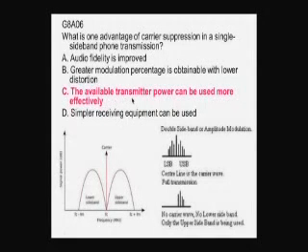And that power can be used more effectively. All of the power now is being used to transmit information. Okay? If we transmit this, we're using transmitter power to transmit a carrier, which contains no information, and another sideband, which contains the same information as this one. So one advantage is that the transmitter power can be used more effectively.